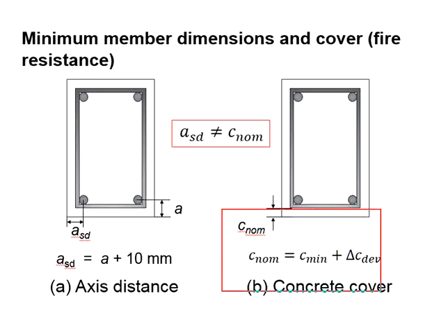As for the concrete cover, it acts as the protective layer isolating the reinforcement from the environment in order to maintain the durability of the reinforcement against corrosion. Therefore, the concrete cover will be defined by the distance from the edge of the member to the first contact of the steel, which is the shear link.